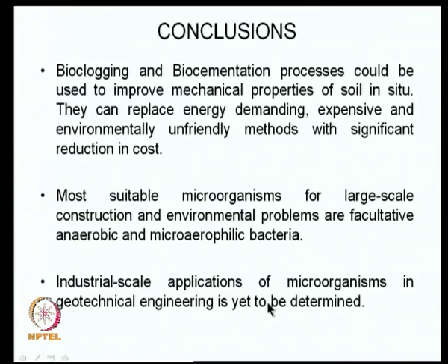It is important that the bioclogging and biocementation processes could be used to improve the mechanical properties of the soil in situ. They can replace energy demanding, expensive and environmentally unfriendly methods with significant reduction in cost. I must also say that experiments conducted by Chu and other authors clearly indicate a permeability reduction of orders of magnitude. Say, for example, instead of 10^-2 centimeter per second, it became 10^-4, which means a factor of 100. There was also a good strength increase.